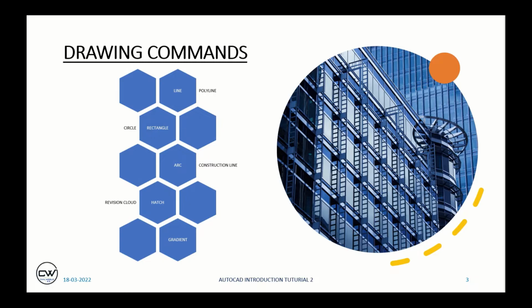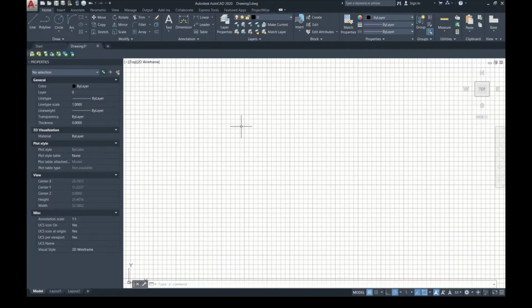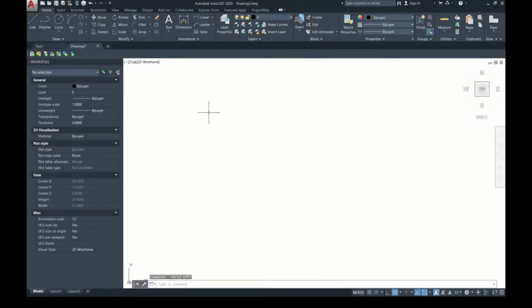I will quickly introduce this AutoCAD itself. So I will switch off grid and everything. So lines you can use here, home menu bar, here draw tool, toolbar, and here you can take from the tools. You can see this is the line, so alternately you can use the L command, so you can take from command or directly from the tool.